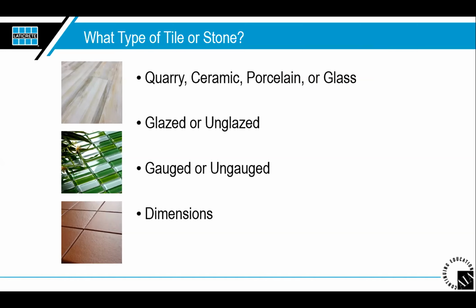Most of the ceramic tile and gauged stone are uniform in thickness, right? The tile and stone of varying thicknesses require setting into a fresh thick bed mortar to achieve a uniform level surface. So we have different types of installation methods. We have thin bed installations. Now it's referred to as not medium bed, but large and heavy tile installations, like LHT installations. And then you also have some methods that are not as commonly used anymore, but we have what we call a wet set method.